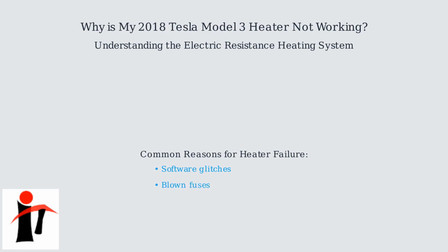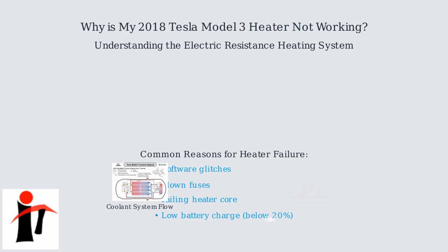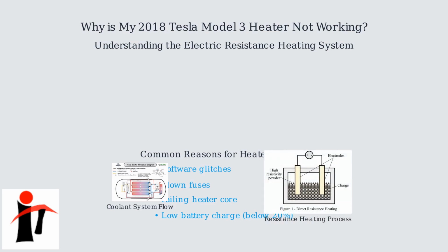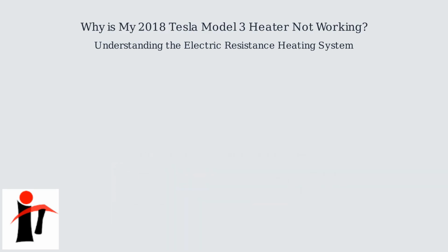Blown fuses can interrupt the electrical supply to the heating system. A failing heater core may not generate enough heat due to corrosion or damage. Low battery charge below 20% can prevent the heater from activating to conserve energy. Intermittent failures can also occur in extreme cold, below -10 degrees Celsius or 14 degrees Fahrenheit, as the resistive heating